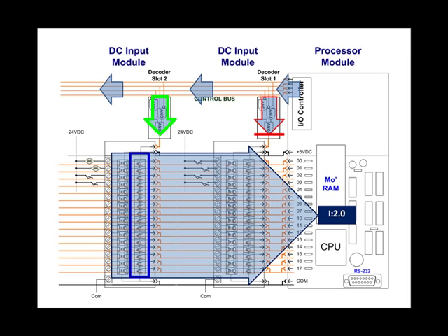Well then, if we can activate input cards one at a time into the 16 input screw terminals on the controller board, we can apply the same technology to the 16 output terminals on the controller board. This processor can only do one thing at a time. It can work with the I/O circuit in memory, or it can execute the program. So why bother doing the same with the output screw terminals? In other words, why create a second data bus and control bus to control groups of 16 outputs?